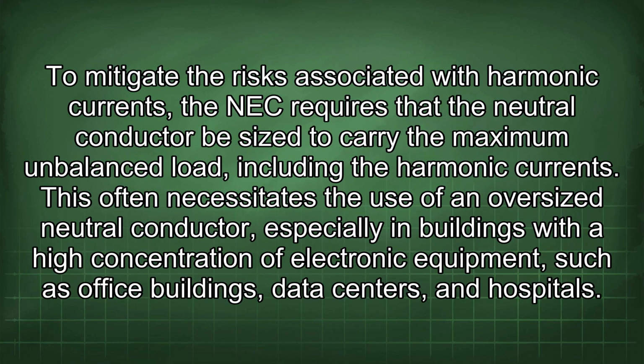To mitigate the risks associated with harmonic currents, the NEC requires that the neutral conductor be sized to carry the maximum unbalanced load, including the harmonic currents. This often necessitates the use of an oversized neutral conductor, especially in buildings with a high concentration of electronic equipment such as office buildings, data centers, and hospitals.